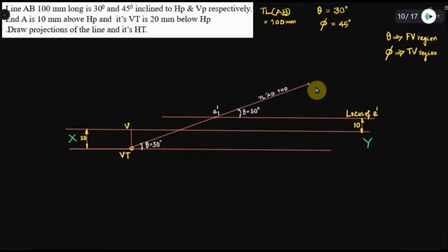So once you have this true length, we got a point, and now the right triangle construction is complete to get the top view length, because it is a triangle involving theta and the true length. Since we have started from VT, we have to project this distance up to V. So I will project up to VT, and thereafter what we require is up to V. And now again we will draw a locus line at this point.